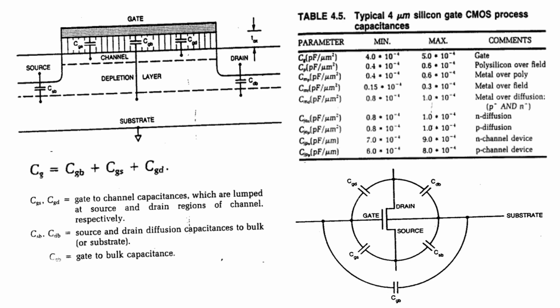And as I said, the MOSFET acts like a capacitor. So here you can see there is a capacitance coming into picture. Okay, and we had seen only two capacitances in the previous slide, but here you can see there is a capacitance between source and body. There is a capacitance between gate and body. There is a capacitance between gate and drain, and capacitance between gate and source. Here we have capacitance between drain and body. Okay, so capacitance means what?